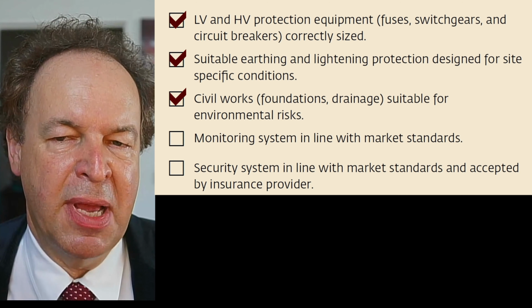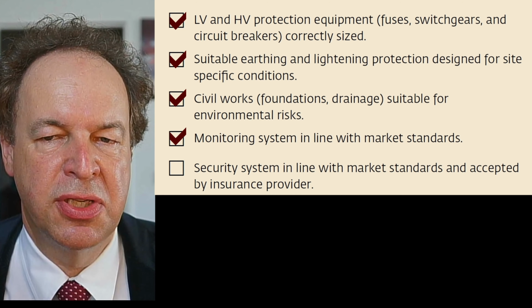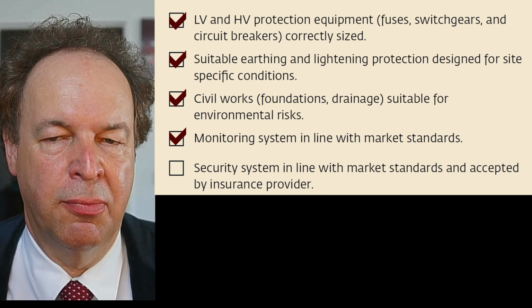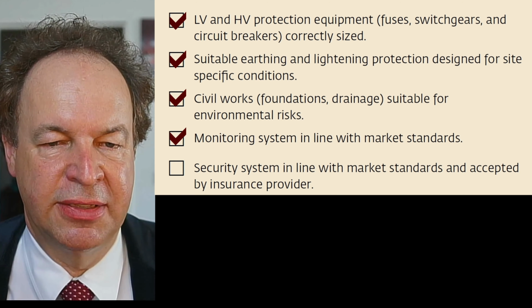The monitoring system, so you want to check whether your modules and your whole system are performing well. You have to install a monitoring system. As mentioned when we discussed microinverters, they allow monitoring even on a single module level. If you have strings or even a central inverter, it's really hard to distinguish which part or which exact component failed if there are some problems in the power plant.